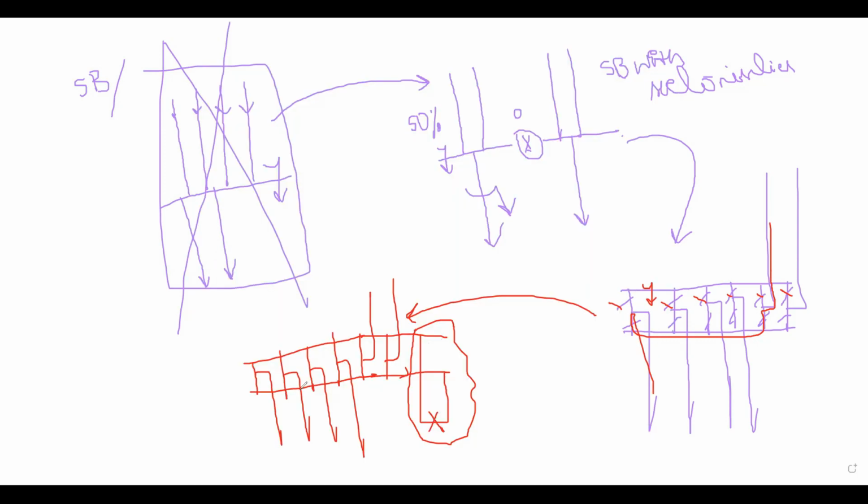Let's see it this way. I'm connecting all the breakers. Now this bus is in the running position. Now I want to shift the load to this bus and take this one into maintenance. Before that, why have I not closed and opened these isolators? Because these isolators cannot be operated in the load condition.